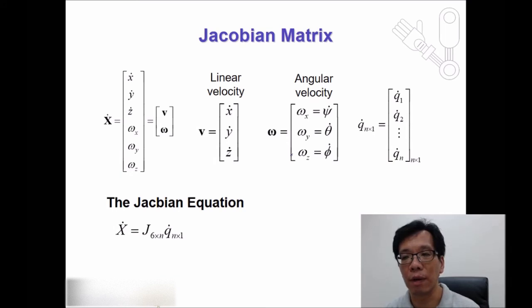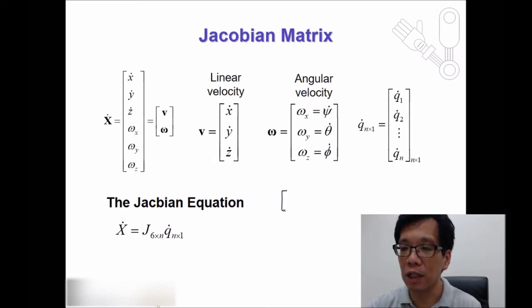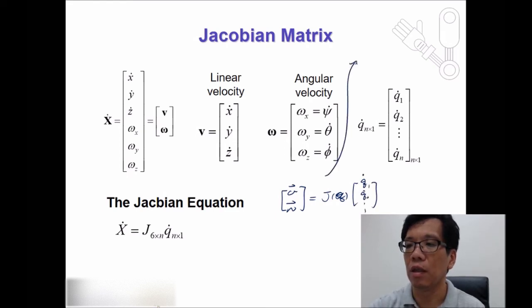Later on, we're going to talk about something a little bit different, because we have velocity and omega, and we know this is going to be a big Jacobian matrix corresponding to Q1 dot, Q2 dot, those kinds of things. But we can actually write V equals J_V times Q dot and still have the same Q dot here.